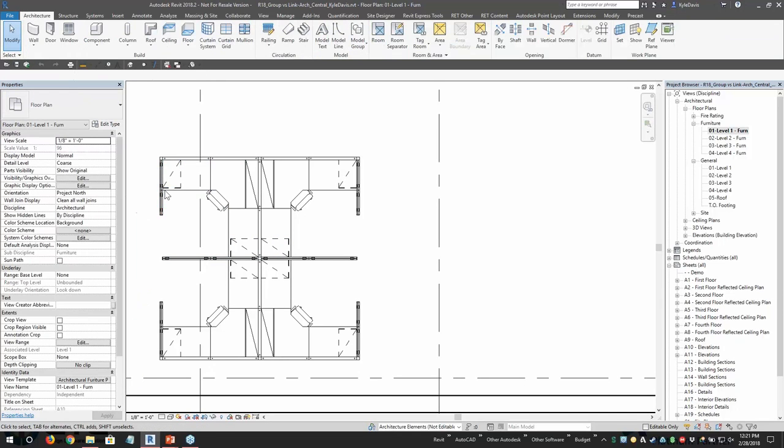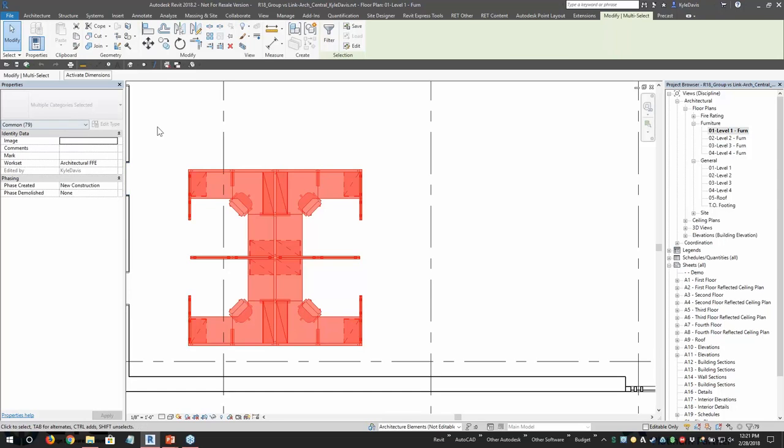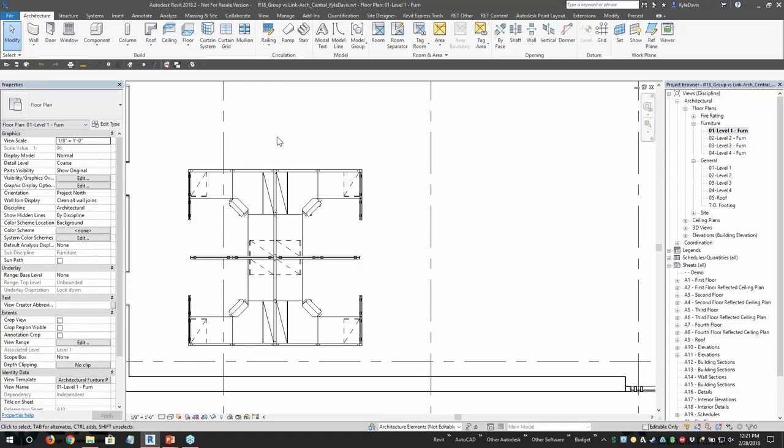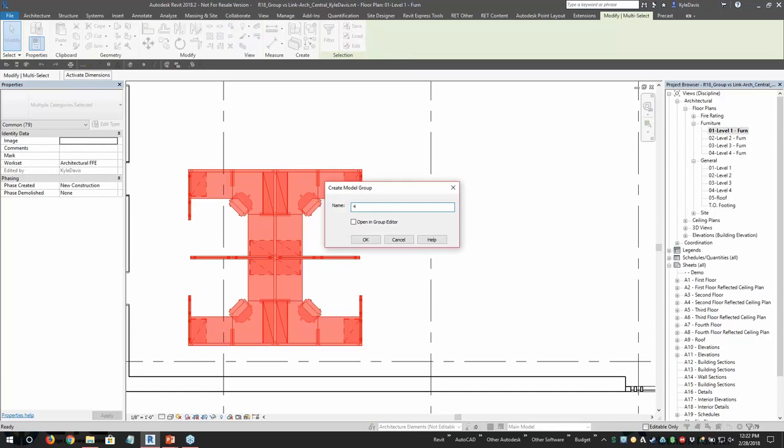So it would make it really tricky. I'd have to make sure I select everything and copy this around. So that's a problem. That's really hard. Sometimes if I go to Windows Select it, I may not have grabbed everything. So if I go to copy that around, that could take some time to copy that everywhere. So instead, what I'm going to use is the group method. So I'm just going to simply select everything here and create a group, and then I'm going to call this something that makes sense. So I'm going to call this Workstations for Layout.